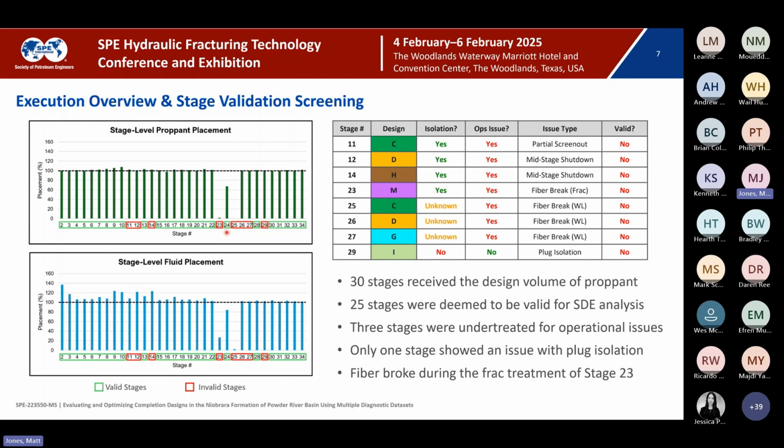Stage 24 successfully perforated about 60% of the way through the treatment. Started seeing some anomalous behavior on the DAS data, decided to stop treating that stage just to prevent further breaks. 25, the cable broke on the final gun of the plug-and-perf run. As you'll see in the acoustic imaging data, we don't think this is because the cable was directly shot.